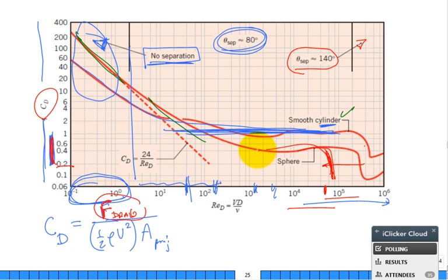What's the dimpling do? It helps it transition to be turbulent on the front half such that the angle of separation goes larger at a lower speed, at an earlier Reynolds number than if it was a smooth ball. Hence, there's less aerodynamic drag. It flies further.